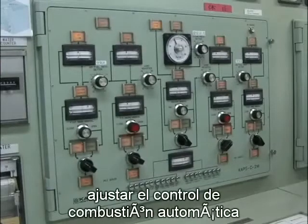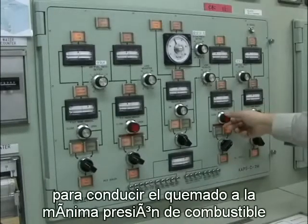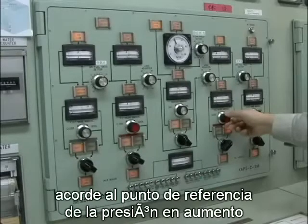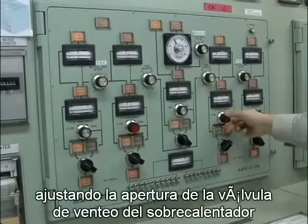In the control room, adjust the ACC to conduct burning at the lowest oil pressure. Conduct steaming according to the benchmark of raising pressure by adjusting the opening of the superheater vent valve.